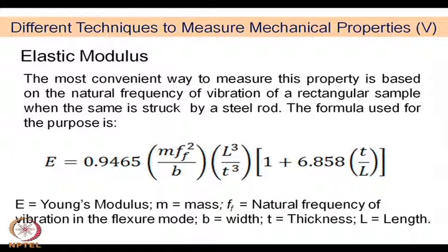That frequency is related to the Young's modulus of the material which is generating that frequency. That is the principle by which the Young's modulus of most ceramic materials is measured, not by carrying out the normal tensile or compressive stress test.